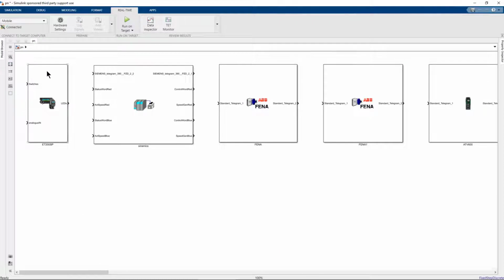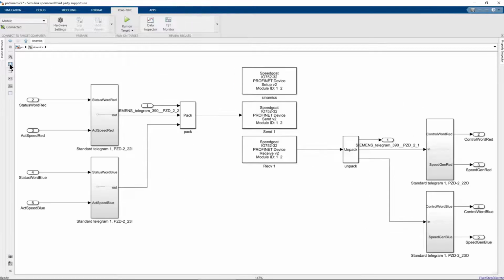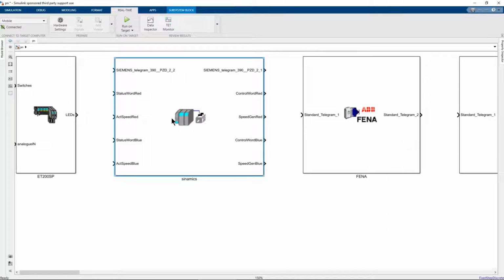The function creates a temporary model including multiple subsystems, one subsystem for each slave. Such a subsystem completely configures the protocol stacks of one node of the multi-node module. It also provides the signals which have been defined in the PLC project. So you automatically get the opposite interface to the variables defined in the PLC. Now you can drag and drop the subsystems to your plant simulation model and connect to input and output signals.